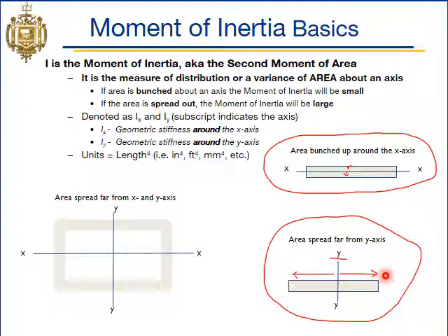So we can prove that if you take that folder and instead of holding it like we have here, turn it sideways. So turn it 90 degrees, this way, and then try to bend it in that same up and down fashion, right? You'll see that it won't bend up and down if you turn it 90 degrees. You could bend it side to side, but it won't bend up and down, right? Because now we're trying to bend it about this y-axis, and essentially that's not going to happen.